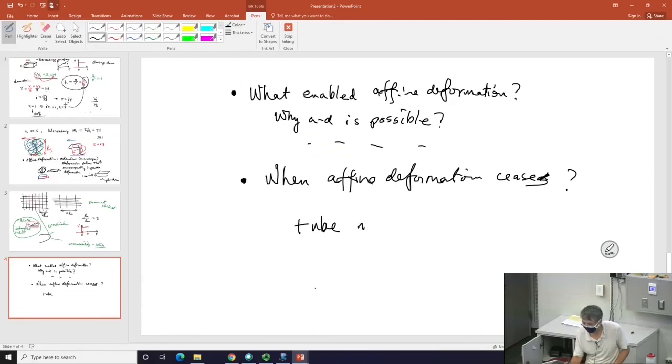The tube model, which we will comment on many times in the future, is the prevailing leading theoretical framework for understanding nonlinear polymer rheology, particularly entangled polymer rheology, which is where the challenge is.